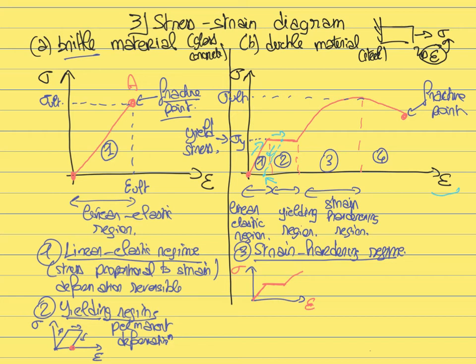So now the question is, what happens after the unloading of this material? If from this point you unload this material, again the deformation is going to be non-reversible, and typically when you unload these materials, the stress will decrease with the same slope as the one it had during the initial elastic domain. So this is what it will look like.